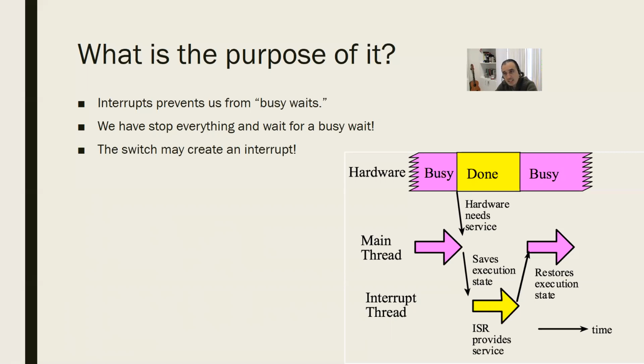However, if we create this so-called interrupt mechanism, what happens is, this is your main code, okay? Your main code is running. So there are lines of code. This is the first line of code. This is the second line of code. So imagine the lines of code are not vertical, but horizontal in a sense. So you're running your lines of code. This is line 10, line 11, line 12, 13. At line 14, while you were executing line 14, by chance, you don't know you're executing line 14, just by chance, somebody pressed the switch.